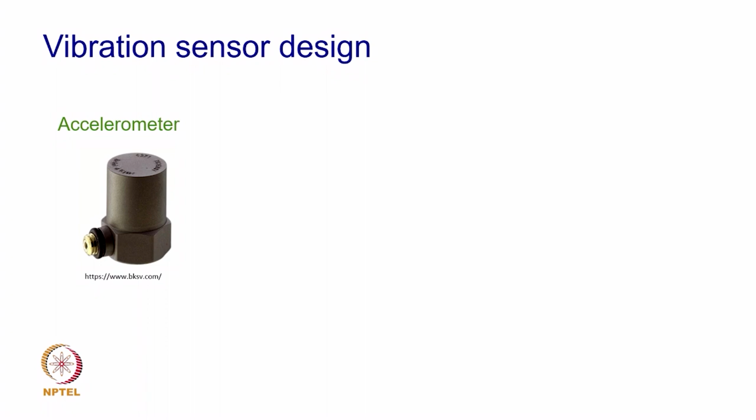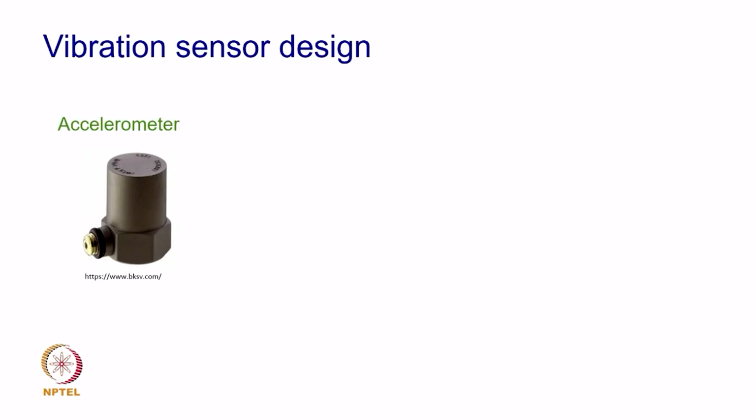So, it is best suited and can also be useful where seismometers are used. Of course, seismometers are typically for very low frequency measurements. So, they are common in building vibration, bridge vibration, and those kinds of applications, but the accelerometer, from a mechanical engineering perspective, is the de facto sensor which is used. So, it is going to be important and interesting to see what the accelerometer design philosophy is. It looks like this, but for us it is important to know what is inside this casing.